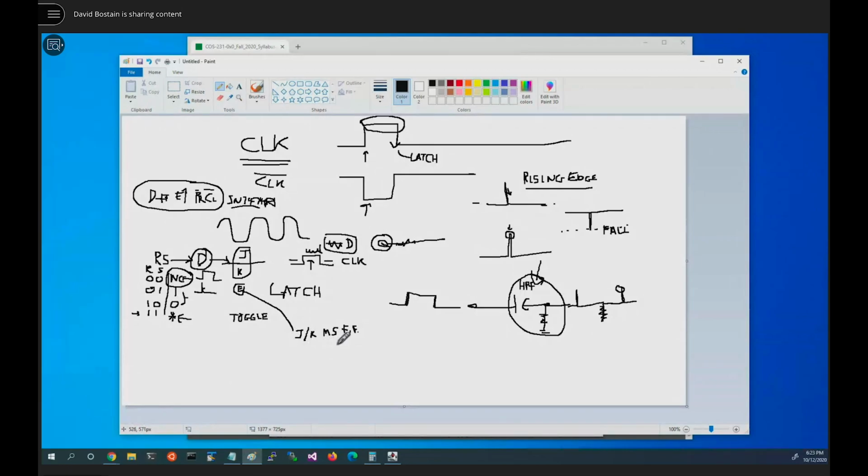It will actually have what appears to be edge triggering, most often on a falling edge. Now, the pictures of it, the schematics of it, very often will not show this correctly. It's just traditional that we know what this chip does. So sometimes we let them slide a little in the schematics.